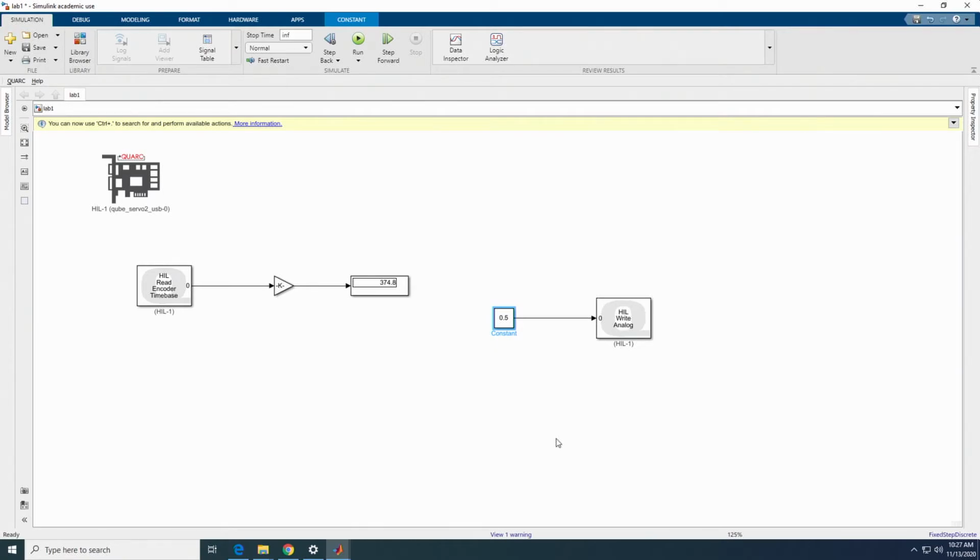Next, I'm going to be creating a stall detection subsystem, which is going to prevent any harm to the servo. What it does is to monitor whether or not an input voltage is being applied to the servo and whether the shaft is rotating or not.